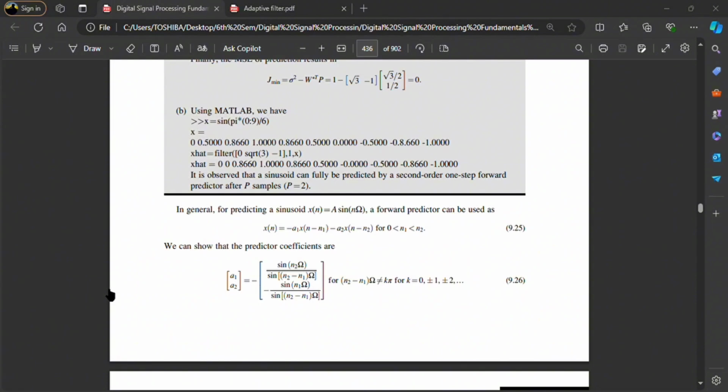Here you can see the block diagram of this, in which we have the idea behind a closed loop adaptive filter: a variable filter is adjusted until the error, the difference between the adaptive input and the desired signal, is minimum. The least mean square filter and the recursive least square filter are types of adaptive filters. There are two input signals to the adaptive filter, which are sometimes called the primary input and the reference input respectively.